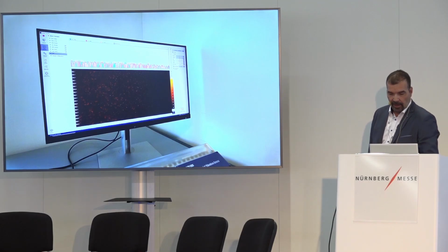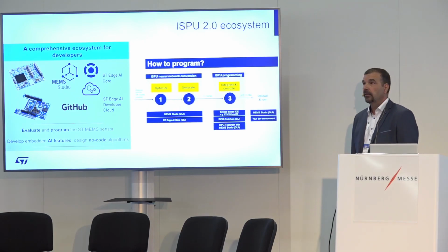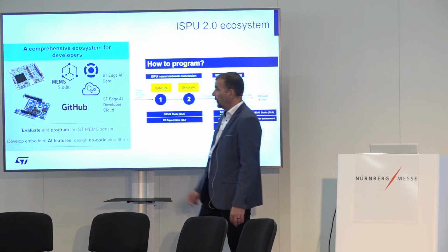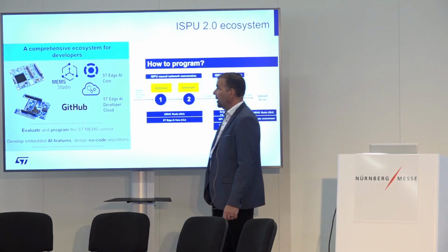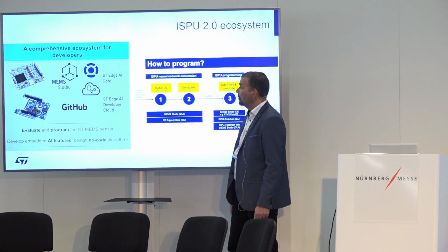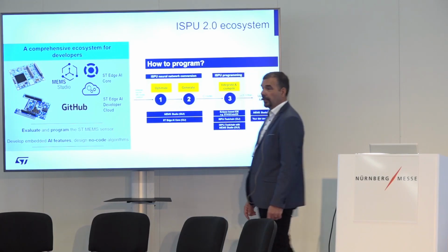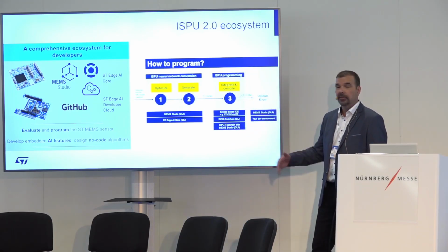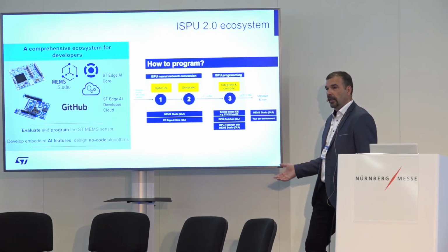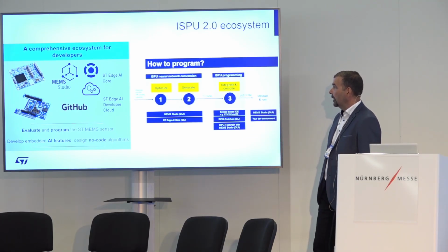Now, I am approaching the last section of my presentation, which is about the tools. Of course, you would like to develop something with our sensor. So what we are offering is a set of demo boards. You can see some of them here. We are also providing for free so-called MEMS Studio. It is the GUI I was showing on the previous slide. And we have also some set of tools which are also touching AI algorithms, which you could run in the ISPU. So, for example, if you would like to have some classification in neural networks, you can do it. You can run them in the ISPU. It does not need to be only the FFT calculation.